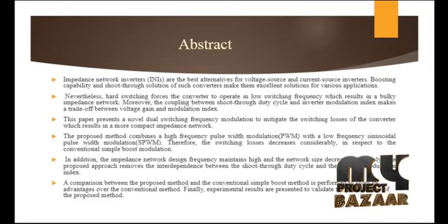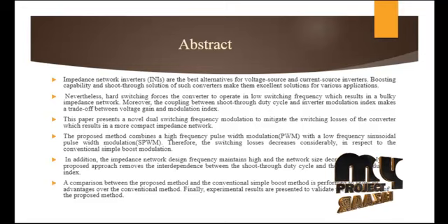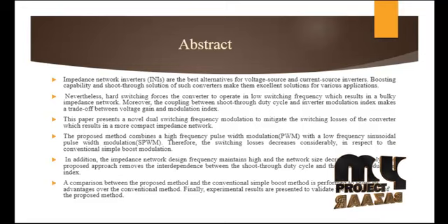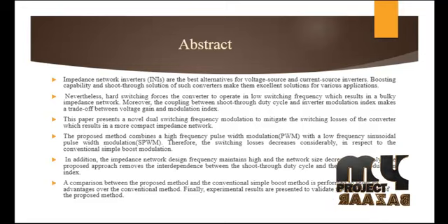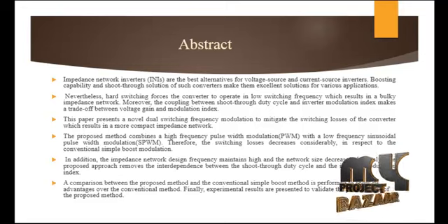The proposed method combines a high frequency pulse width modulation with a low frequency sinusoidal pulse width modulation. Therefore, switching losses decrease considerably with respect to conventional simple boost modulation. In the impedance network design, the frequency remains high and the network size decreases.